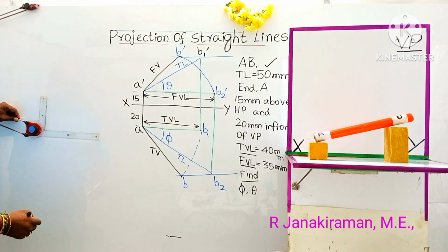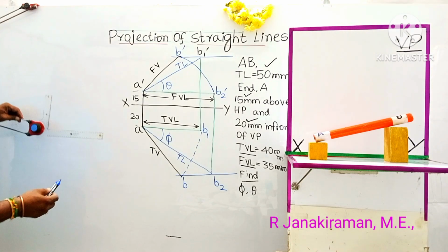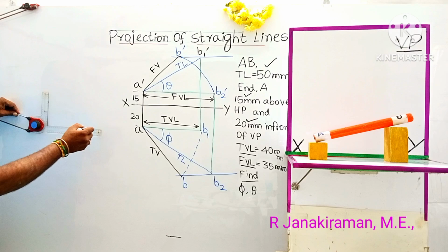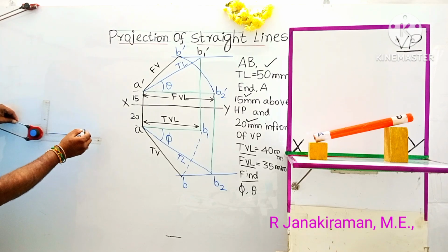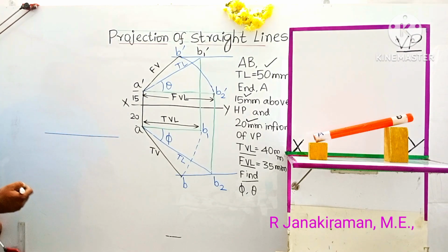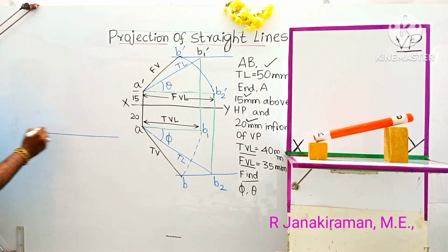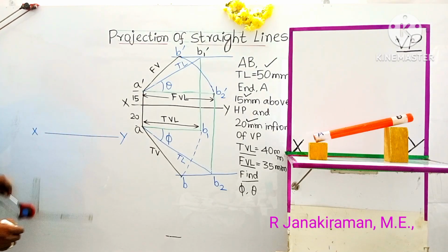So first you draw the reference line called the XY line. Next you are going to draw the FAD diagram. Take your drafter scale, the longest scale of your drafter. Draw one horizontal line called the reference line. Mark X and Y. This line shall be drawn using an HB or 2H pencil.